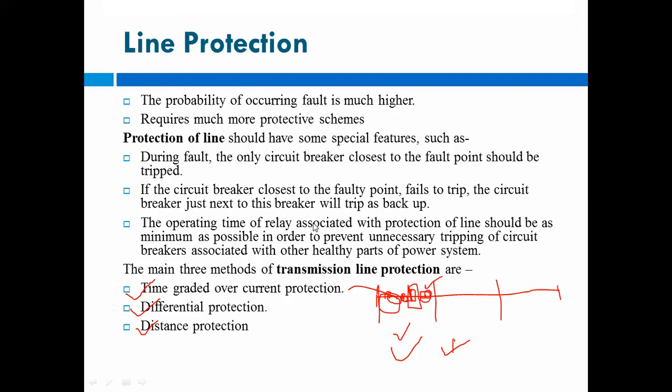When we are protecting the line, it includes not only the transmission line but all the other elements also, so we have to protect that line. For that we use time graded protection, differential protection, and distance protection. Also, we use backup protection for the protection of the lines.